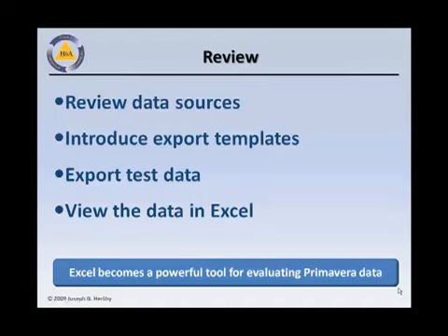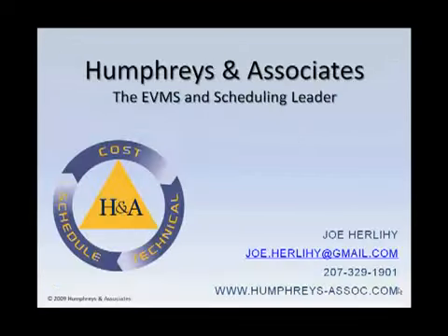To review, we've looked at the data sources available in Primavera to export. We have introduced the export templates to get the data into Excel. We conducted a simple export of test data, and then we looked at that data in Microsoft Excel. From all this, we begin to get a feel for Excel becoming a powerful tool for evaluating Primavera data outside of Primavera.